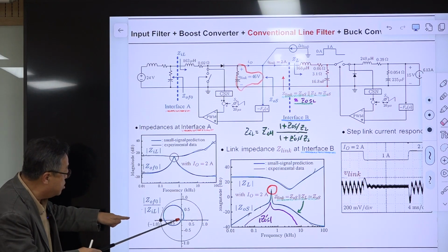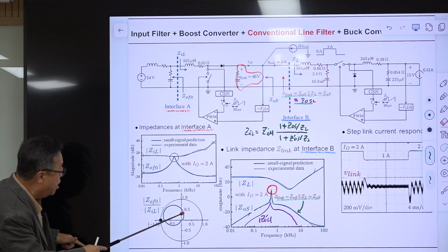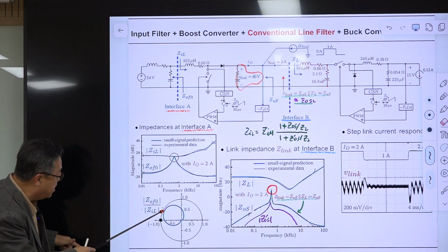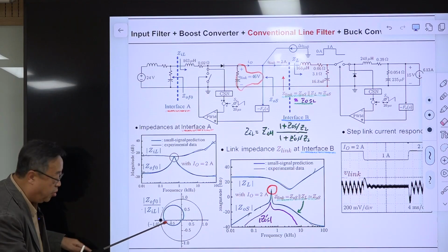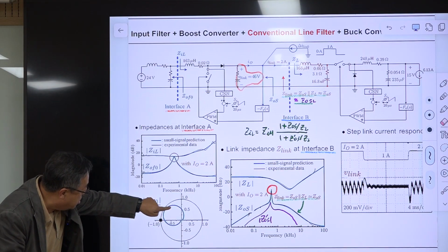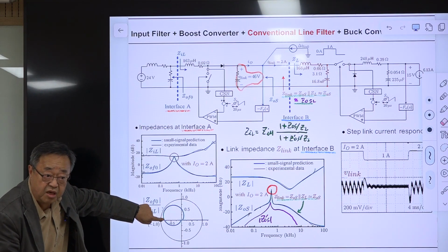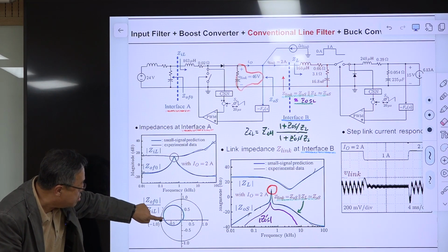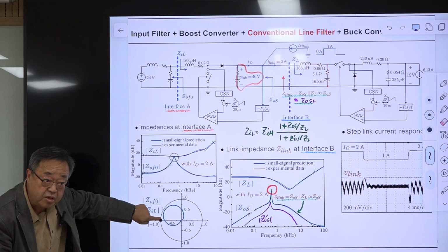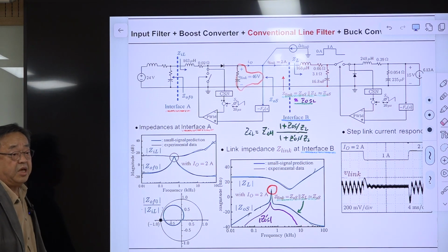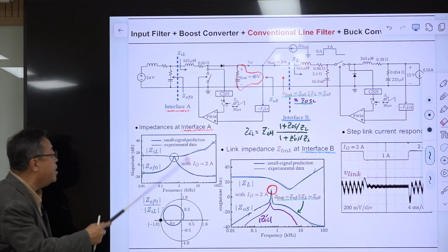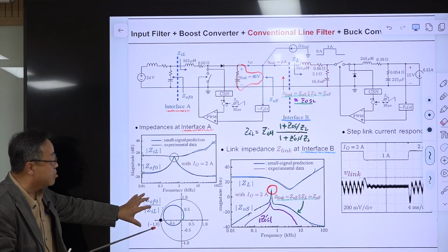So this is the polar plot of this loop gain, and the loop gain does not encircle this one, but it dangerously approaches the vicinity of this. It goes near this point, so it is almost unstable. So this can be considered unstable, and there is overlap that indicates the system is unstable.